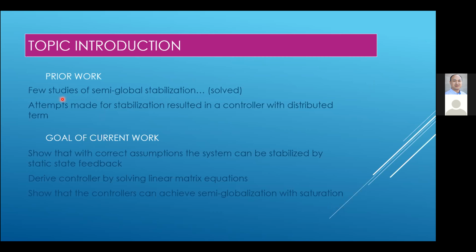There were one or a couple of attempts made for full global stabilization, but it resulted in controllers which had distributed terms inside, which were developed by using Lyapunov equations-based feedback. But again, because of the distributed term, they are very difficult to compute.